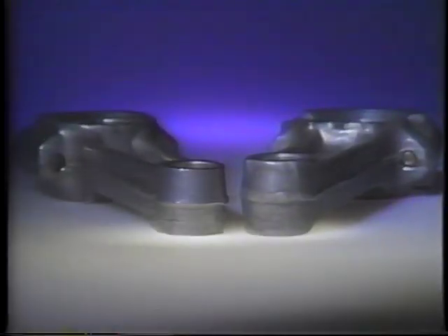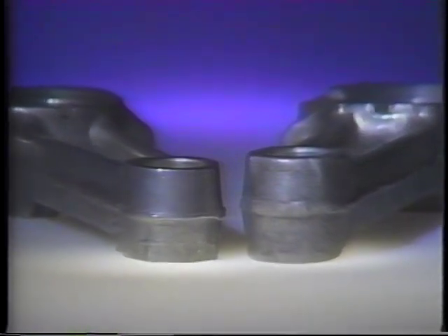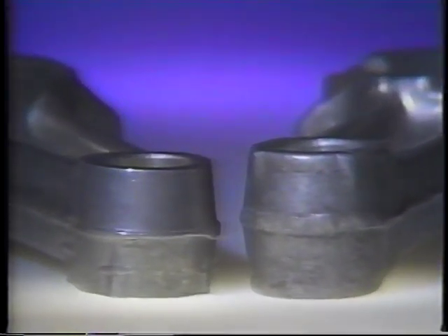Connecting rods can be made of aluminum or steel. They must be very strong to withstand the tremendous downward thrust of combustion pressure on the piston head. With the crank and bottom of the rod spinning around in the crankcase, oil is splashed on moving parts to lubricate and protect them from friction and wear.